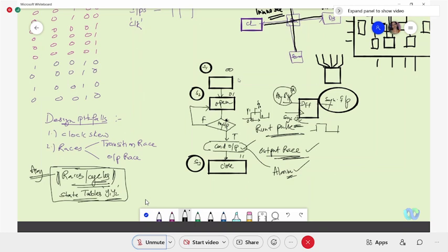Now see here, say I take this as 1 0. Just for explanation I'm taking, I'm giving an AB value as 0 1. It needs to go to a 1 0 transition. That means two variables need to be changed in order to have the state 2 to state 3 transition. Two state variables are involved and two state variables need to be changed.